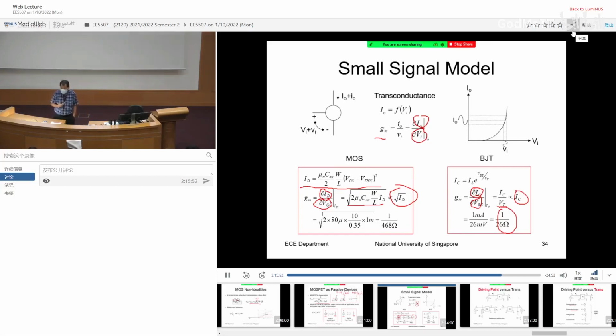Isn't all of us like small current? What is the problem with small current? Come again? Drive capability or bandwidth. Right? It's proportional to the current. The higher the current, you can operate faster. You can have higher bandwidth. Lower current, bandwidth gets limited.